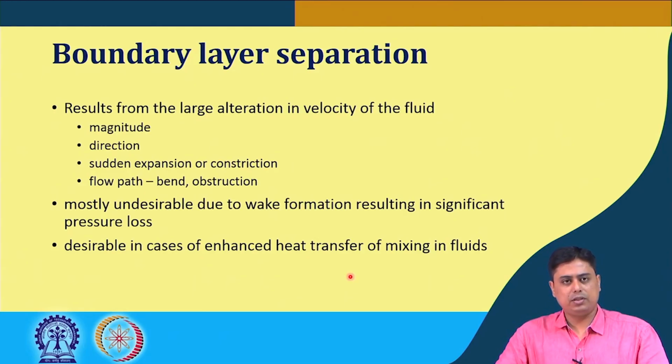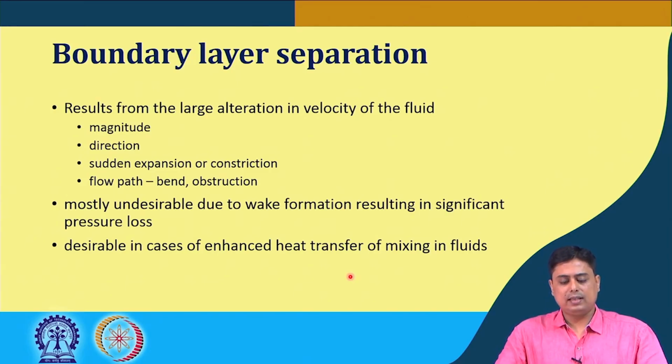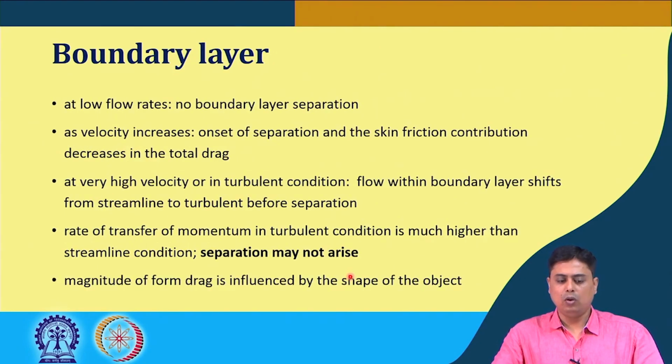Okay. So, boundary layer separation is mostly undesirable due to this wake formation that results in significant pressure loss, but it is sometimes desirable in cases where we require enhanced mass transfer or mixing of fluid. Okay. So, in those cases this kind of wake formation or local turbulence is helpful and helps us to have the enhanced conditions. Now, at low flow rates there is no boundary layer separation.